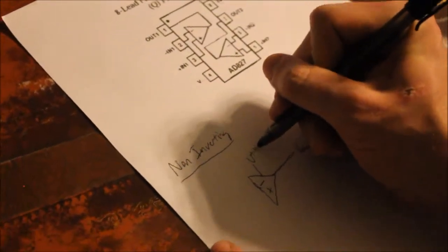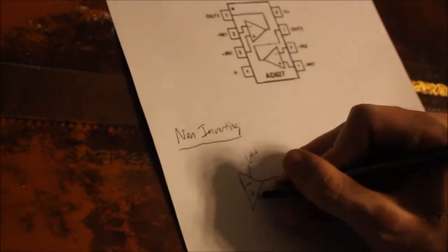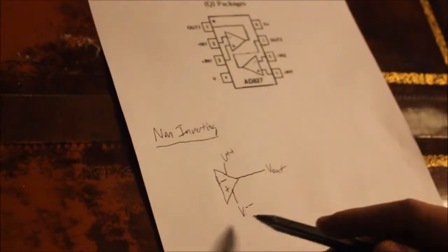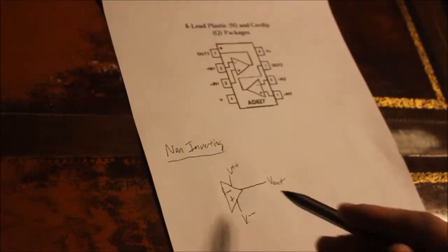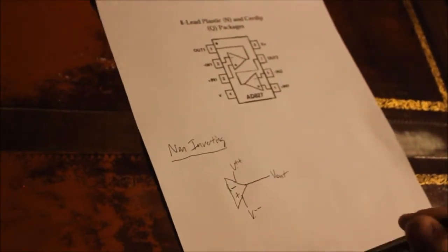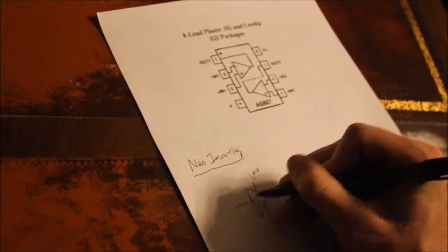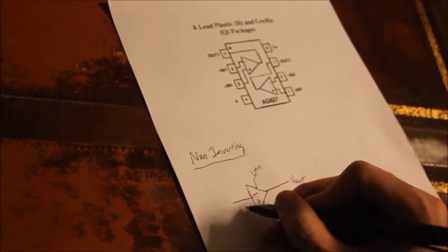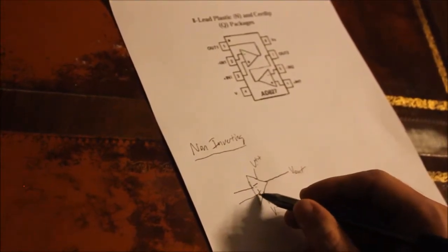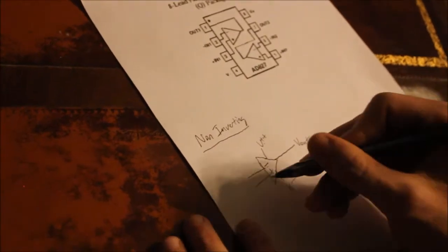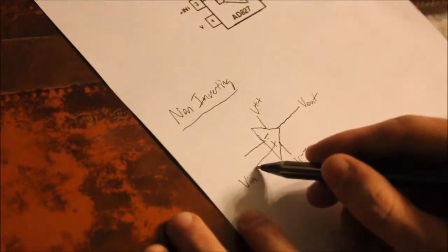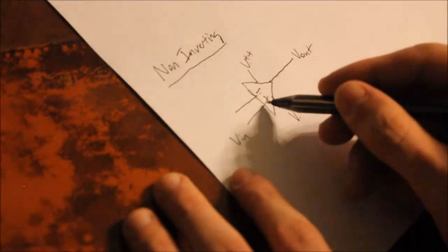this. So the op amp is an active circuit element, meaning it requires an input voltage. In this case, two actually. We have the high voltage input and the low input voltage. Those are kind of the parameters the op amp works around. It can only output this high or this low. Here we have this goes into the negative sign, as you can see on the op amp, so that's the inverting input. This goes into the positive sign, so that's the non-inverting input. And I'm just going to put, since it's non-inverting, our Vin signal goes straight to the non-inverting input.